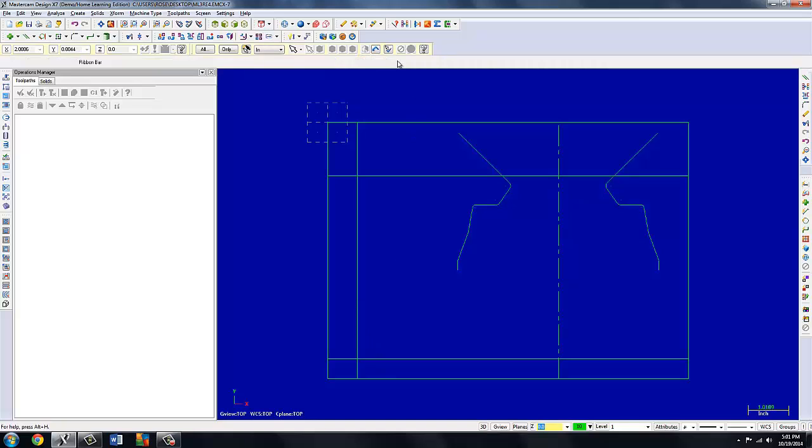I've got a couple of arcs I can use. They are actually dimensioned as center points, so I'm going to go to create circle center point. The first one has a radius of 2.5. Enter. I'm going to go to my fast point and just put these coordinates in. It's 4.5, comma, 0.625. Enter, and that makes the, from our plateau, sloping down handle there. I'm going to accept that one. I'm going to do another one.